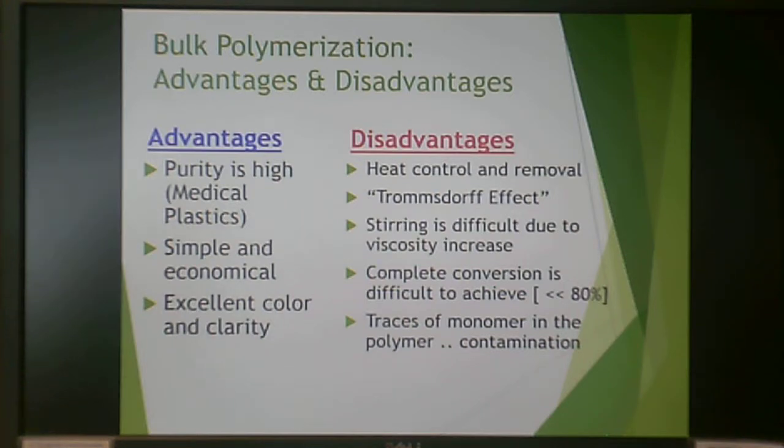I've had autoacceleration happen to me in the laboratory when I'm using 25 grams. It makes a mess. If you do that when you're dealing with tons, you can have an environmental or health disaster. So controlling the heat of a polymerization reaction is not trivial. Also, you have to stir it. Chemical reactions are little tiny games of bumper cars. Functional groups have to be next to each other, so that propagating chain end, for example, has to be near a monomer for that monomer to add.